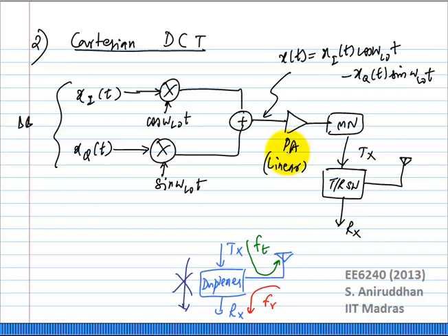We are talking about anywhere from hundreds of milliwatts to several watts, and this power actually couples magnetically, or maybe through the substrate, maybe through the power supply, to other circuits, and that causes interference. Whereas in an FDD system, you are transmitting and receiving all the time. You are not doing this periodic on and off. Because of that, you will find that FDD systems are much more common. But I am pretty sure there are many cases where you can realize the TR switch on chip.